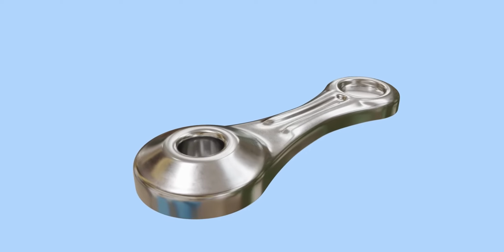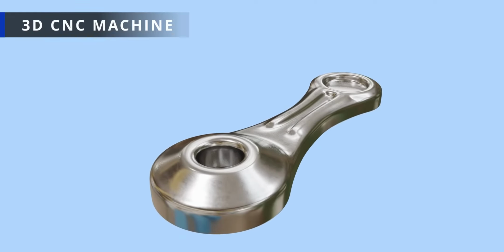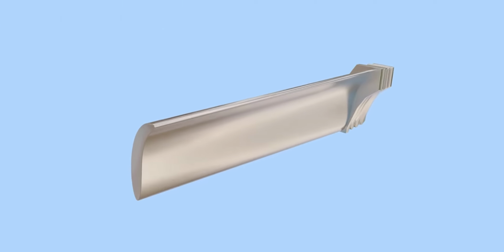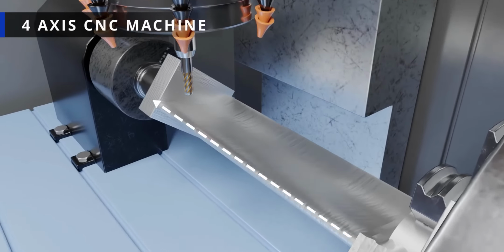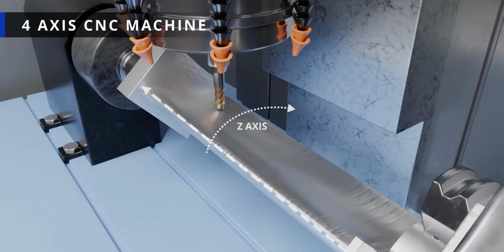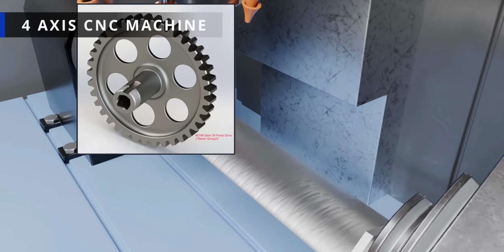What about this shape where the depth varies gradually? This requires the tool to move in the Z direction along with X and Y movements. This is an example of 3D machining. Now, what about the blade of a steam turbine? The only way to produce such a shape is by spinning the part in the Z direction along with the tool movement in X, Y, and Z directions. This is known as 4D machining, as shown in these visuals.